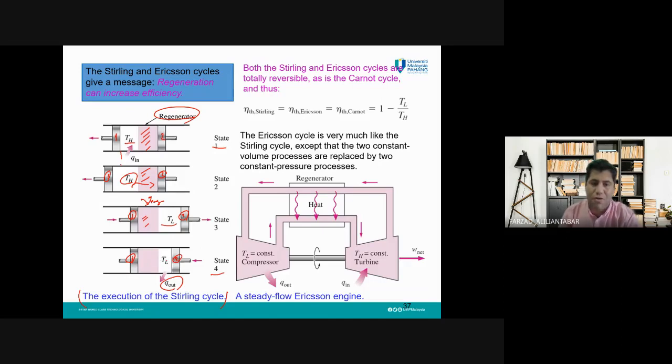How about this gas which we have here? The gas will again travel through the regenerator until it goes back to its initial state. During this transfer of the gas through this porous substance, the Q which was given to the porous substance will be given back to the working fluid, and the temperature of the gas finally here will be TH.